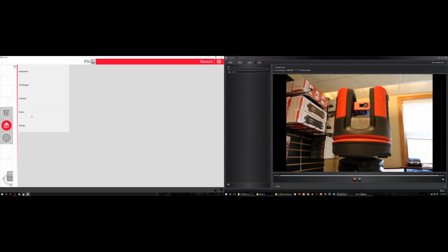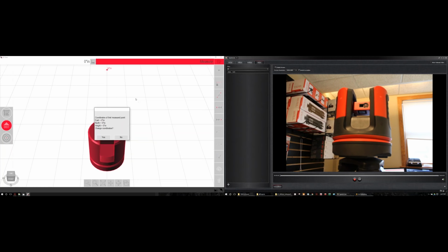So if we go to settings, import, export, if you go to coordinates, used to be in version 3 by default, this was set to some crazy numbers, 13,000 inches, 20,000 inches, blah, blah, blah. But what it really is, is the 0, 0, 0 point of your drawing. So the first measurements that you take are close to that 0, 0 point.